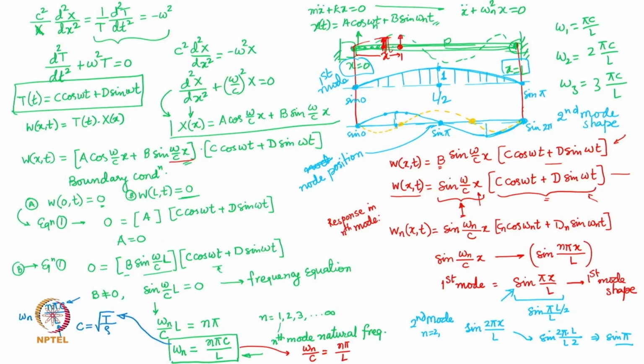So when you tighten those knobs, basically the tension is being increased. Okay, the same happens with percussion instruments, musical instruments, where you essentially increase the tension to raise the pitch or frequency of the sound. This is because the natural frequency here is directly proportional to the tension in the string.